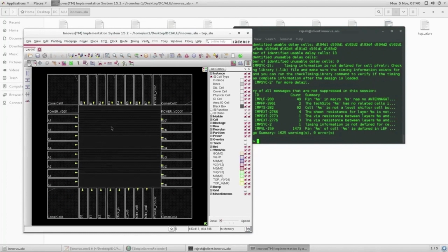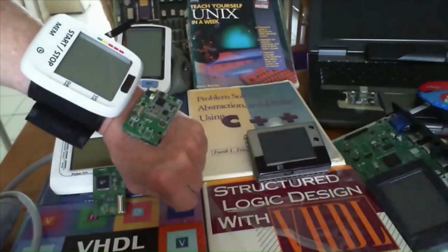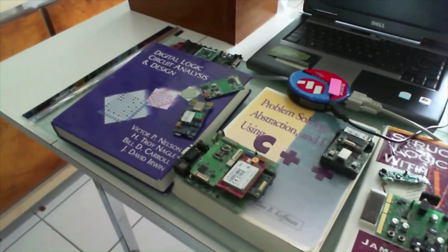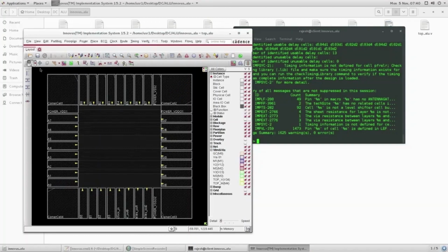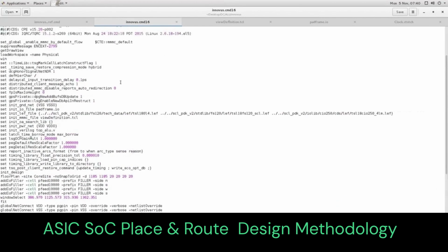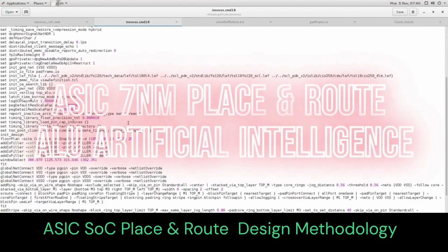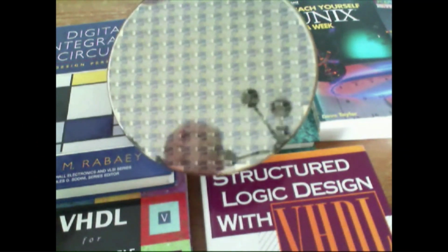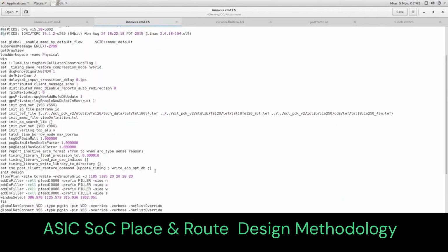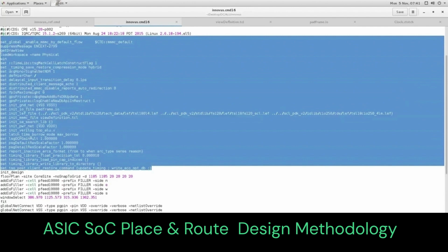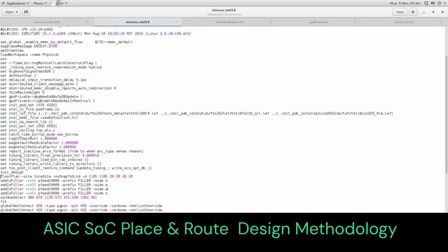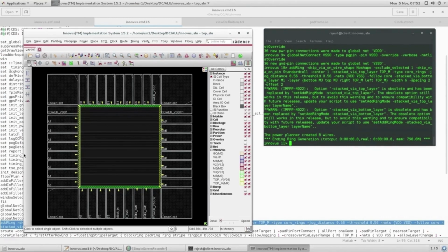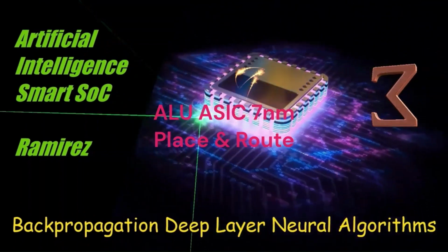Second, generate constraints for placement on the basis of a timing analysis done using idealized clock arrival times at latches and estimates of wire load and RC delay before physical design. Third, perform an initial placement to determine an improved basis for constraint generation and optionally to fix the placement of large objects. Fourth, generate new constraints for placement on the basis of a timing analysis done using the wire load and RC delay values derived from the initial placement.